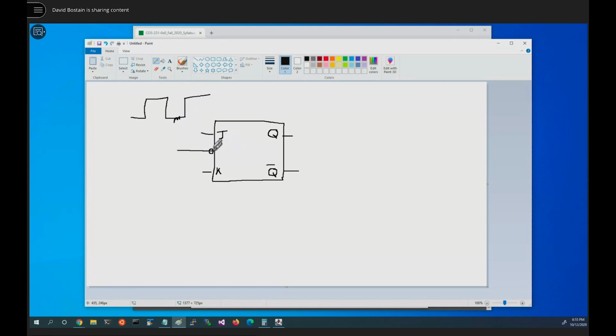Except, as I mentioned earlier, in the case of JK flip-flops, all bets are off on how the clock will look. It's to be assumed, unless you're told otherwise, it's probably an MS flip-flop, and you should assume it's a low-going, what appears to be edge-triggered clock on the second stage.